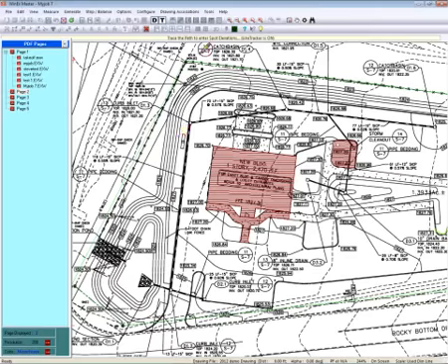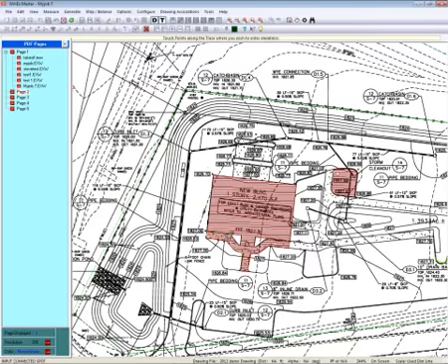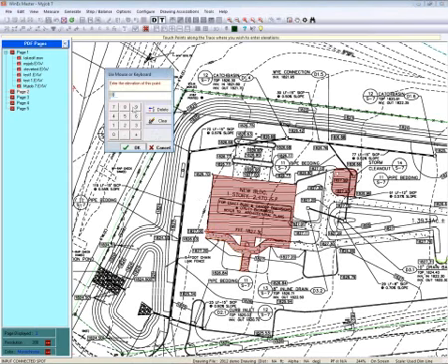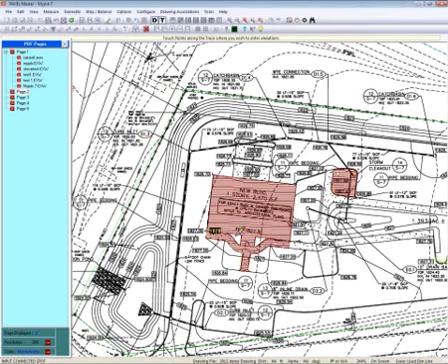And again, software is telling me what it wants us to do, trace the path of where these spot elevations are going to be. So maybe I'm going to put one here, put one here, here, and here. And when I click Finish, now it tells me touch points along the trace where I want to enter those elevations. And my cursor, although it's a little difficult for you to see, is actually locked along that line. It won't let me put elevations in anywhere else. So I can put in, let's say, 1828 here and hit OK. Here I can put in 1826. I'll stick with that. And here we'll do 1824 and 1822, and I'll hit Finish.